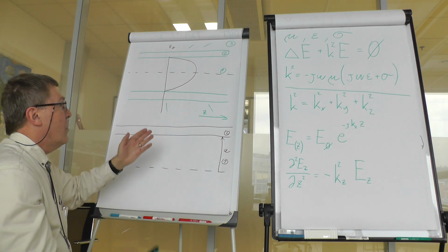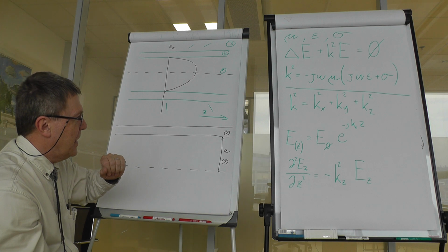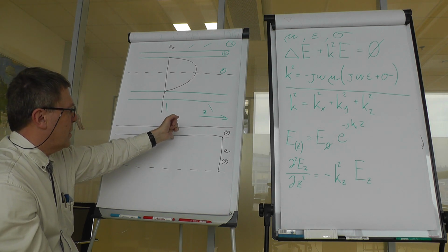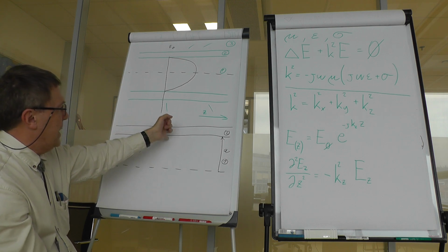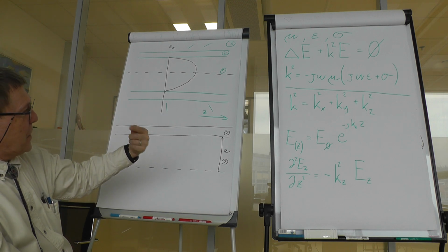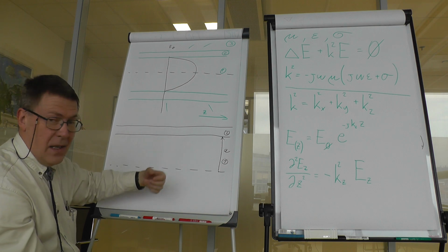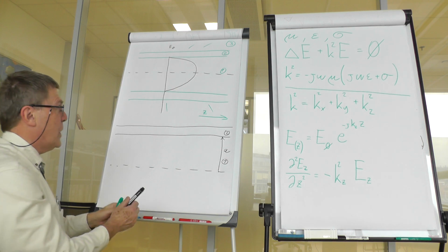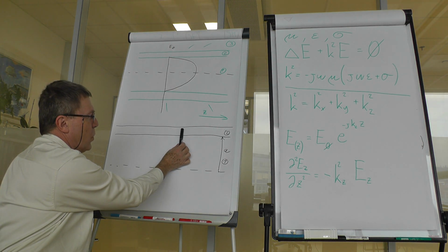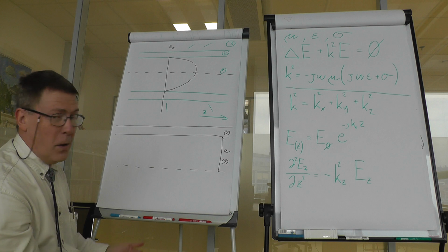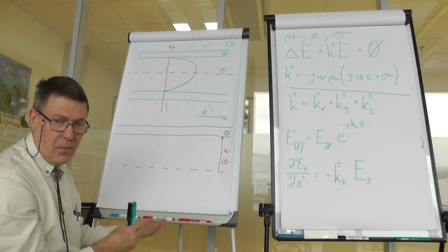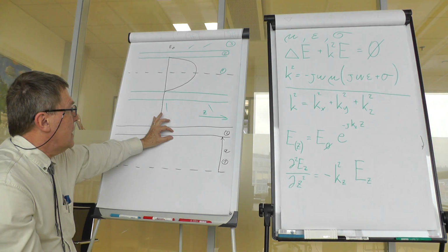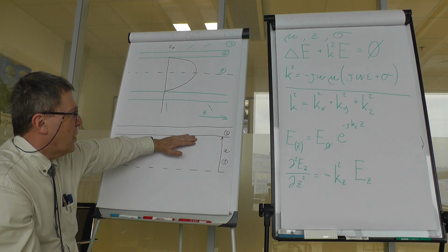Second, we could derive equations for tangential components running into or out of the paper. Then we have another set of boundary conditions. And finally, we could derive conditions for normal components of E and H, or E and B, and that's another set of boundary conditions.